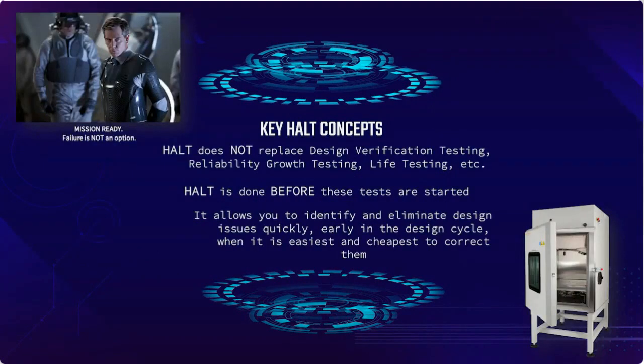Now, here are a few more of the key concepts to help you understand what HALT testing is all about. And this first one really is a very important one. HALT does not replace any of the design verification testing, reliability growth testing, life testing, all of the tests that you normally do on a product before product release. Those tests have very specific and critical purposes, and they must be conducted.